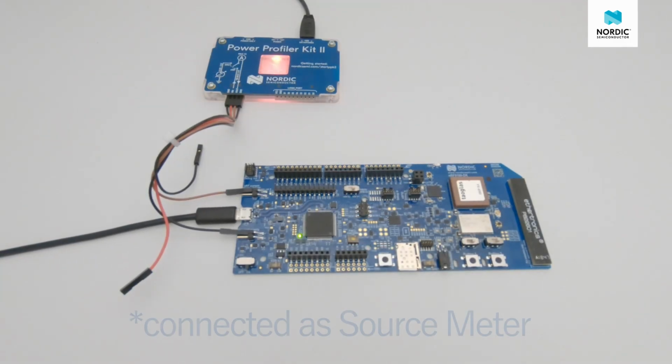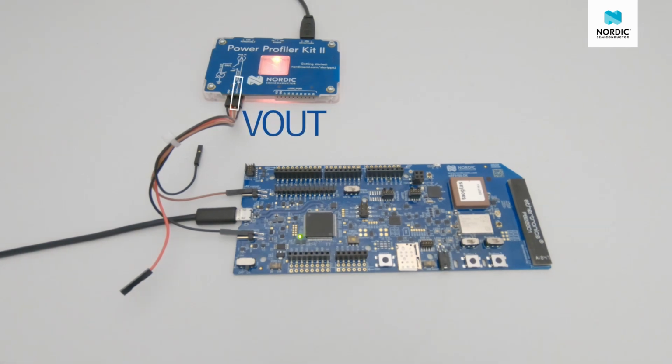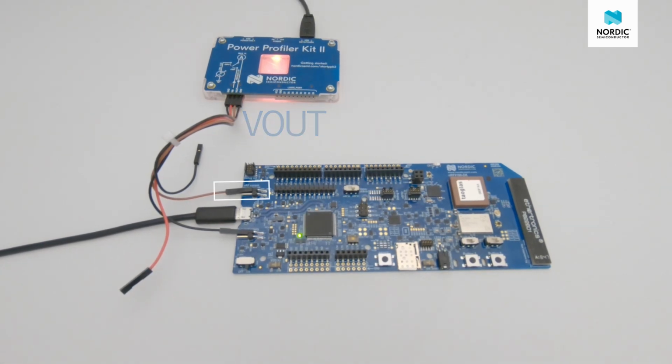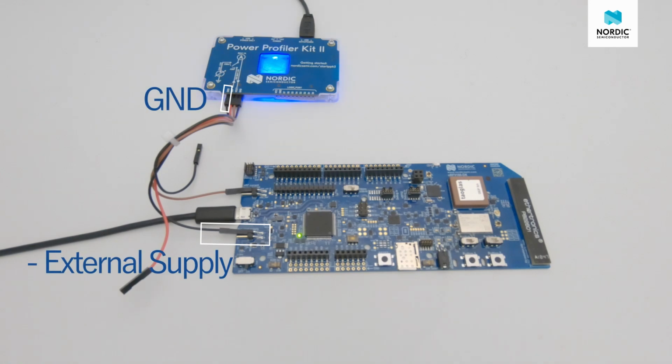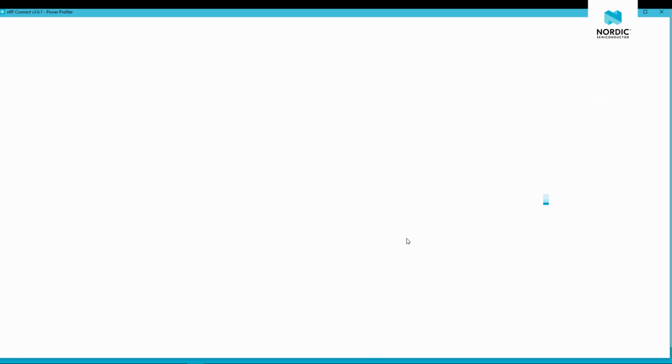So here you can see how I have connected the PPK2 to the nRF9160. I have the brown VOUT connected to the VDD nRF on the nRF9160 and the ground connected to the minus on the external supply. So let us open the Power Profiler tool. It's in nRF Connect for Desktop.